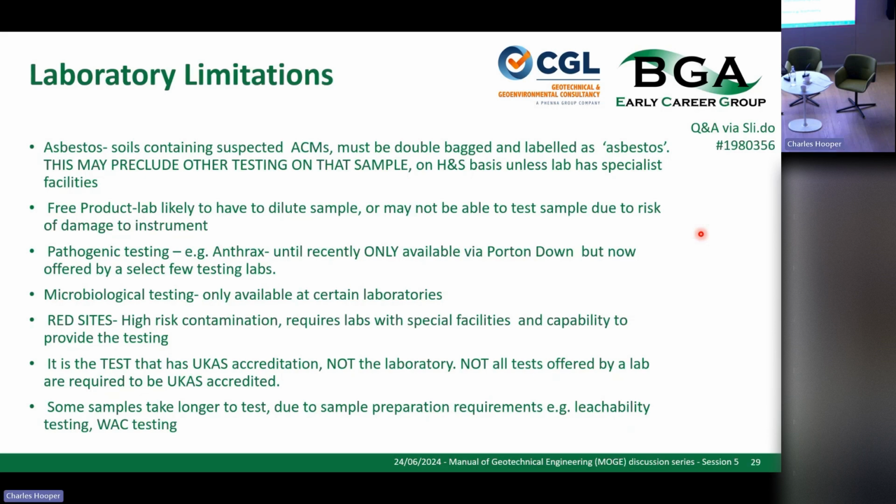We have sites that are called red sites. They're the most contaminated sites, the ones where the risks are the highest. Quite often, if you are on a red site, you're going to have a lot more controls and protection in for your drillers and your samplers. You're going to be having people in white suits and respirators.